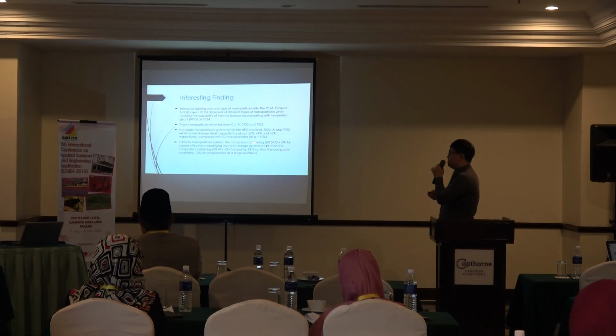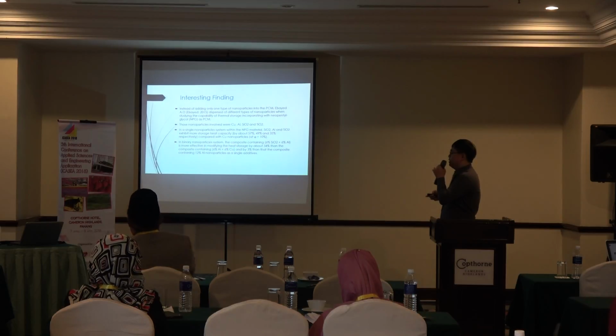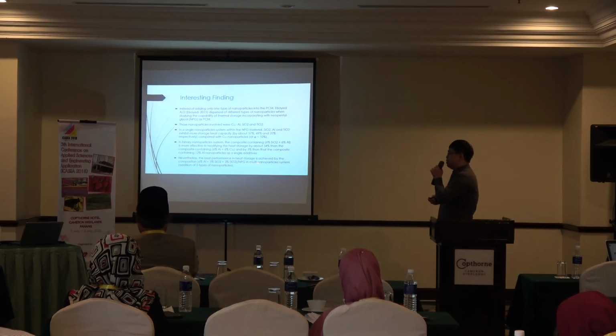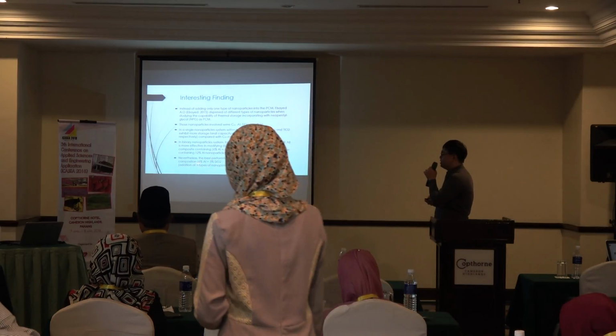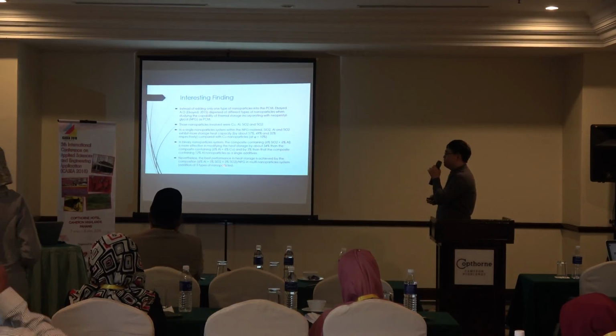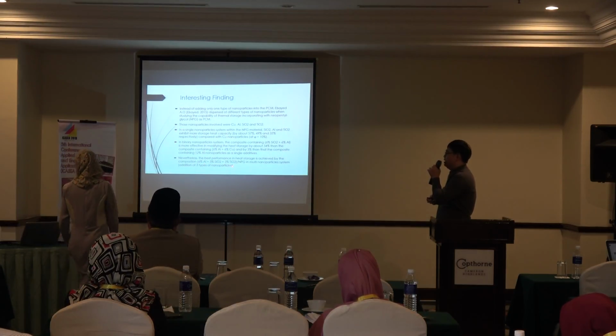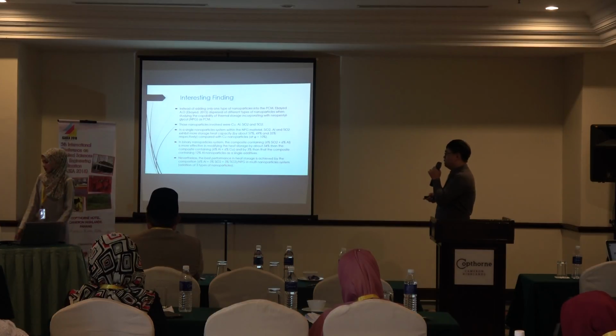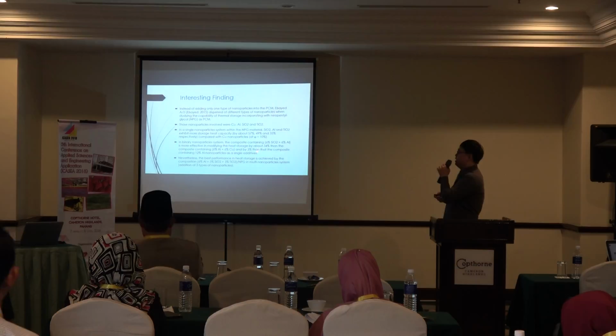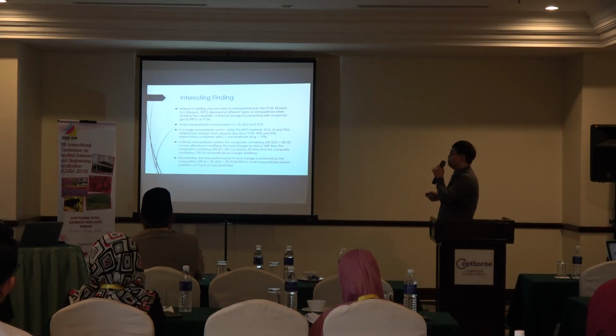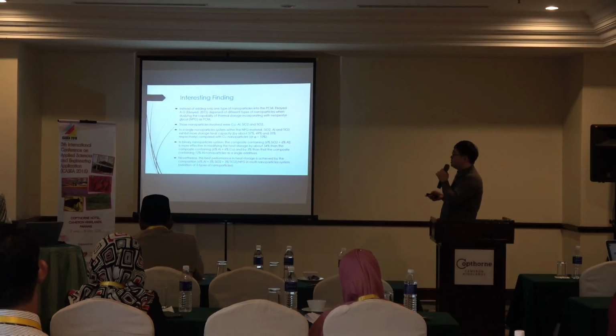And compared to the single system, adding two types of nanoparticles is better than adding one type of nanoparticle. Nevertheless, the best performance is obtained by adding the combination of three types of nanoparticles, which is 6% of aluminium, 3% of silicon oxide, and 3% of titanium oxide into a PCM. So this research has actually opened a gap for future researchers to try to enhance the phase change material more by adding more than one type of nanoparticle.